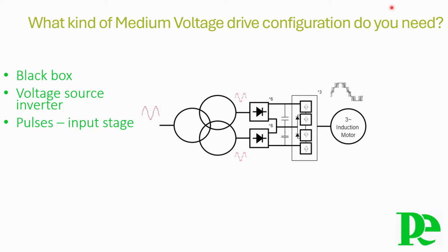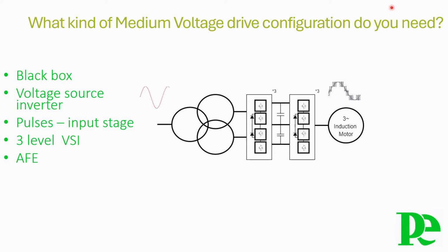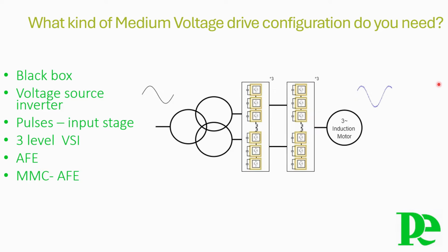An alternative to the architecture characterized by the number of pulses is the active front-end, AFE. Instead of a rectifier or a direct front-end, DFE, we use basically a repeat of the inverter. The active control of the input stage enables a much cleaner input power and provides even for 4-quadrant operation. Finally, combining the modular multi-level version for AFE and for the inverter stage together realizes a high-performance drive with clean in- and output power.